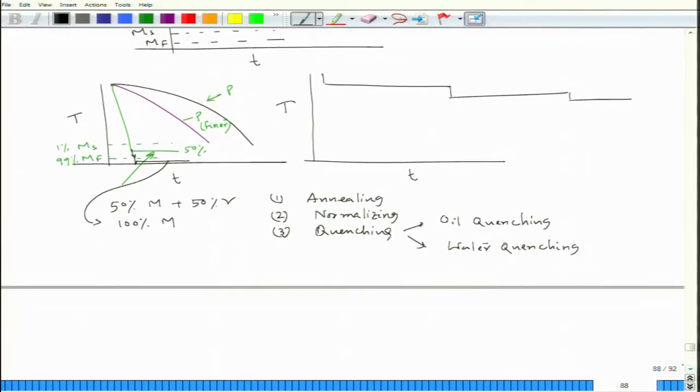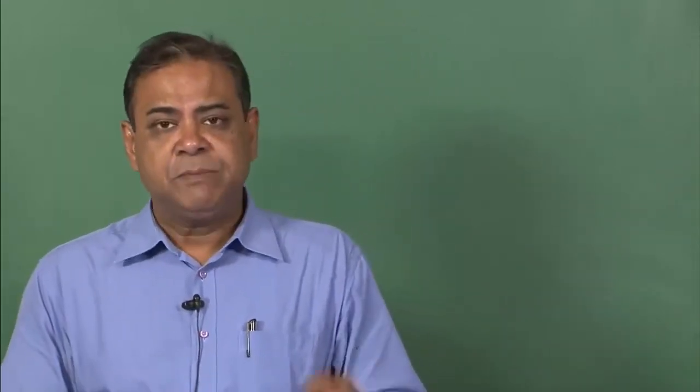Since we have given the example of nuts and bolts, their actual process matters because they have a microstructure of tempered martensite. Now, there is a particular term called tempering. This is also an important heat treatment practice. Whenever we form martensite, it makes the sample surface very hard, but it is also associated with brittleness.